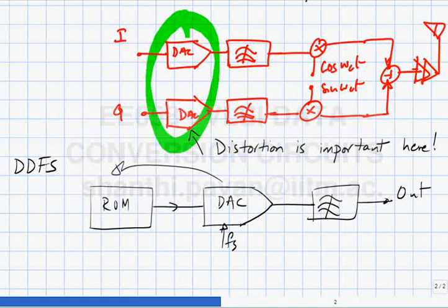So in other words, you can get at least a sine wave with 10-bit precision over the range from 0 to fs by 3 or fs by 4, definitely before fs by 2, without any major hardware. All the hard work has been done in the DAC.